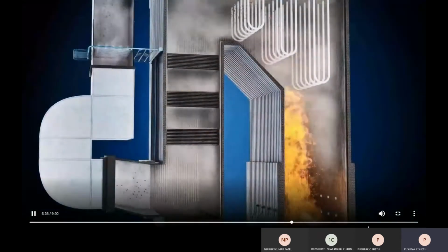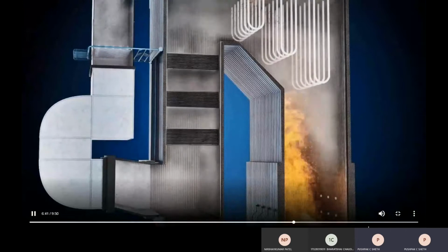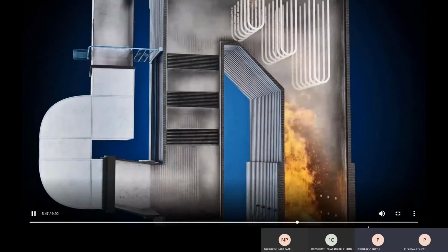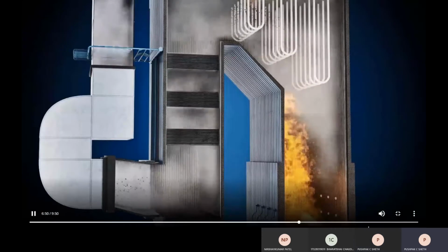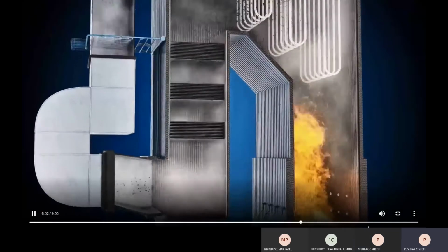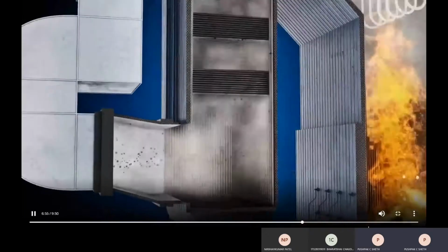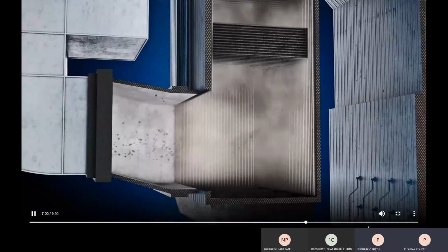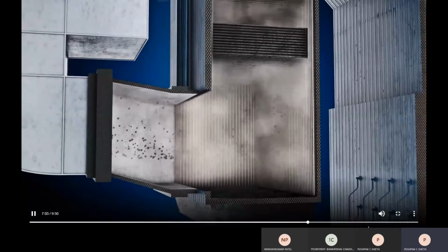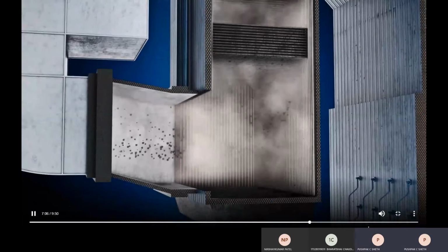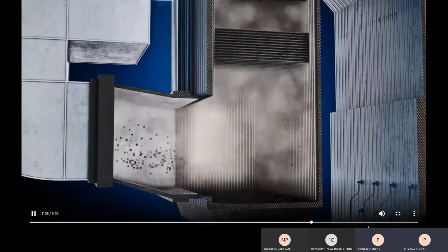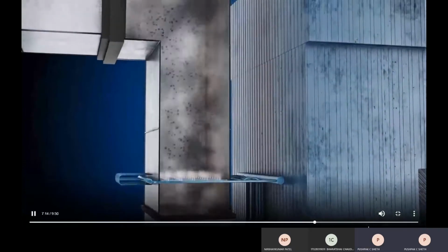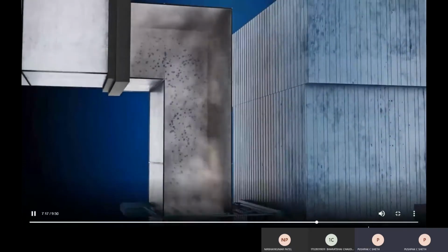While the heavier particles of ash fall to the bottom of the boiler, hot flue gas containing finer particles of fly ash naturally flows up to the top of the boiler and around, down, and out through the backpass section. The last section of the boiler is the economizer. Because of the shape and the flue gas flow path, some of the fly ash falls out here into hoppers. This economizer ash is pulled by vacuum, mixed and sluiced with water to the ash booster station, where it moves to on-site storage. Flue gas, after combustion, exits the boiler and enters the catalytic converter, or SCR.